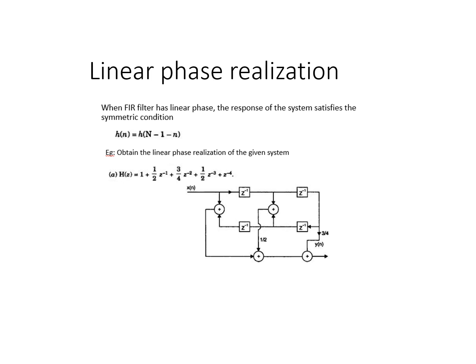So totally the maximum delay required here is z^(-4). So we can write in this form z^(-1), z^(-1), z^(-1), z^(-1). This is the input x(n). So totally 4 delays are there. So initially H(z) we can write as Y(z)/X(z). If we cross multiply this, you will get X(z) into this total term.